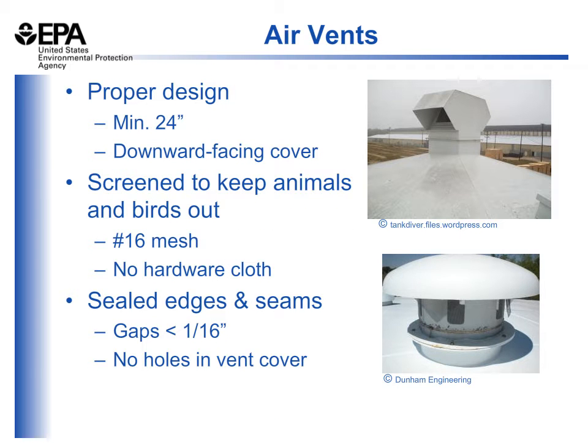With the exception of pressure tanks, all tanks have an air vent that basically allows the air to come in and out of the tank as the water rises and falls. This is intended to alleviate any pressure issues. If an air vent becomes blocked, water draining from the tank could form a vacuum on the inside, and that may be sufficient to collapse the tank walls, causing a catastrophic failure. So therefore, make sure you inspect the vent regularly for any type of blockage.